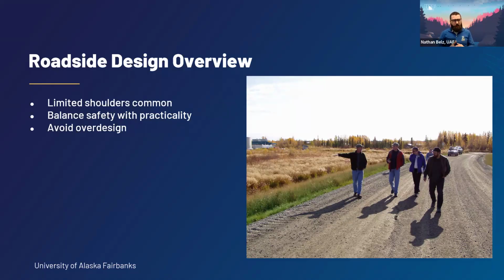Having flat road sides can be difficult. Large clear zones, or putting in traffic barriers, is probably not cost effective for these types of roads either. Again, if we're keeping them at low design speeds, there's not going to be a great need for large clear zones. So designers should just apply their judgment in some of these roadside design features. We want to avoid over design. The purpose and intent, as Billy noted about the ultra low volumes guide, is to really scale down some of these things, to make them more appropriate and contextualized within these smaller villages.